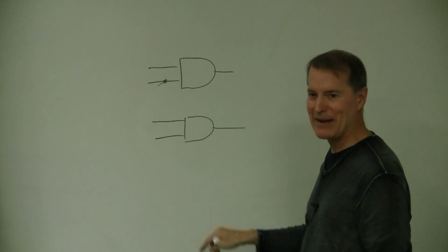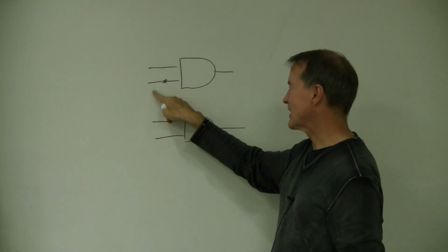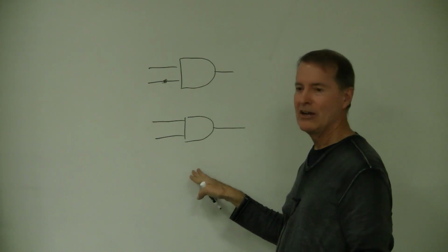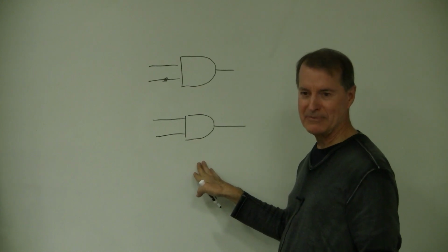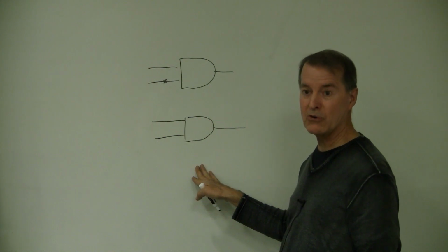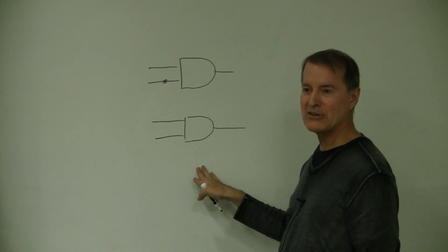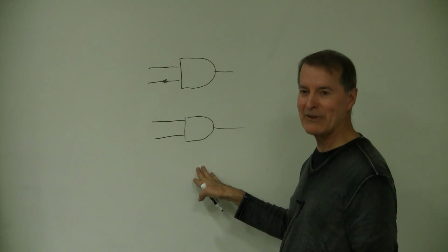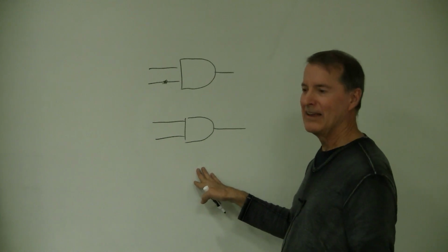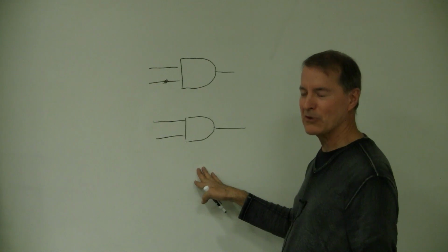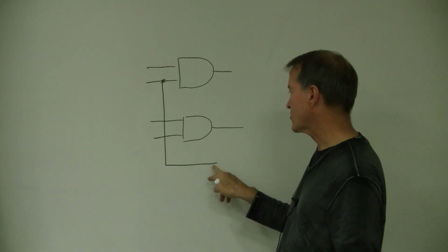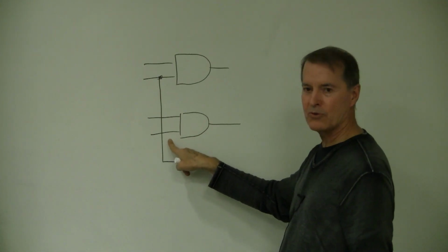Look, you guys, let me just be kind of professional about this a little bit. When you draw a circuit diagram, first of all, the lines never curve. I've never seen a logic circuit drawn with curved lines. They're always either horizontal or vertical. So if you want to get in the habit of having your stuff look really professional, I don't care. I'm not going to count off or anything. Then your wires should all either be horizontal or vertical. And furthermore, if you want a wire to go this way, you can just go ahead and have it cross over these.